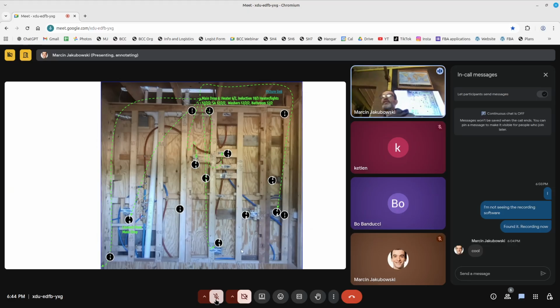With the water fittings, you can simply quick connect using SharkBite fittings. With wires, the general strategy is you have to leave some kind of a pigtail from one module to the next, or wire up all the boxes in there and leave a pigtail out for main interconnection, or do the routing after the fact, where we leave a utility channel at the bottom. We do not puncture any studs.